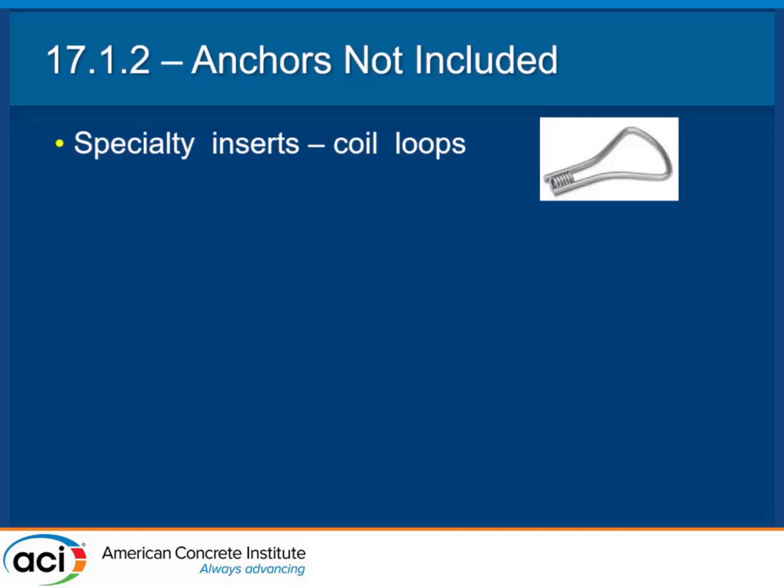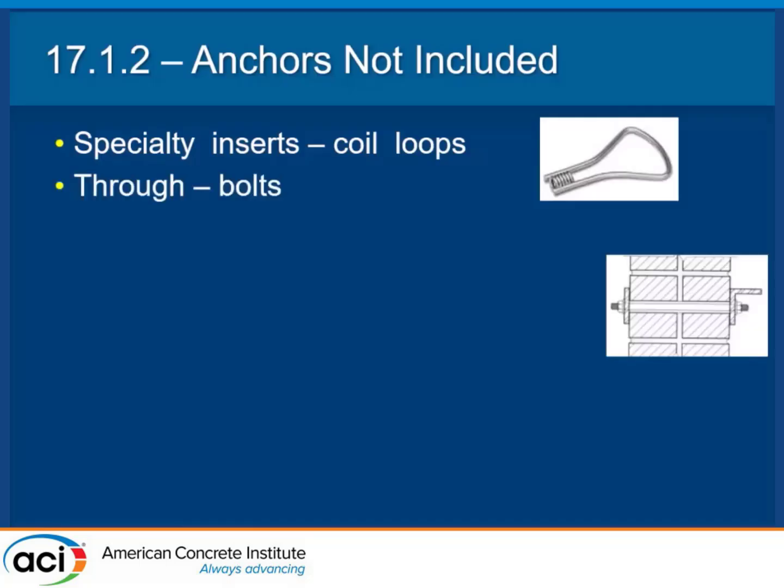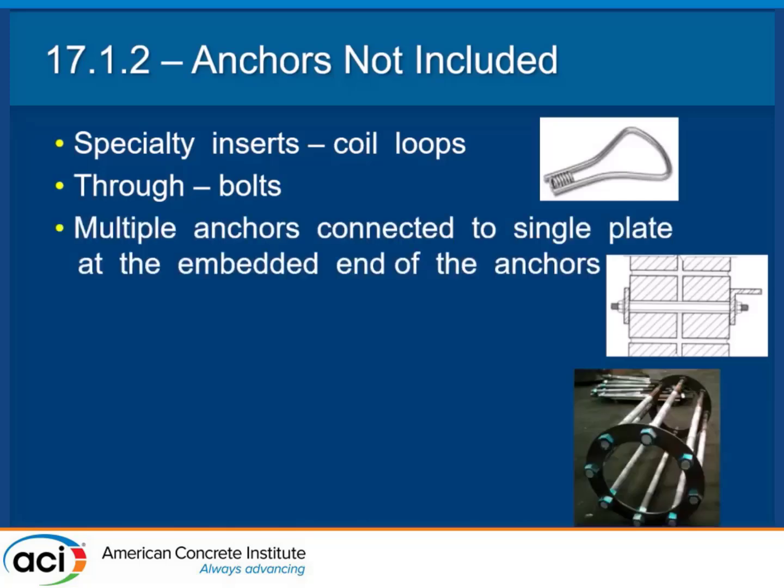But, like precasters, they love these specialty inserts and coils, but we do not cover that in the code. Through bolts, we don't cover. Now, often I get questions on through bolts. You can use a lot of the principles, and you're going to get the visuals today to help design a through bolt, but the code does not really help you on that, or does not have any code requirements.